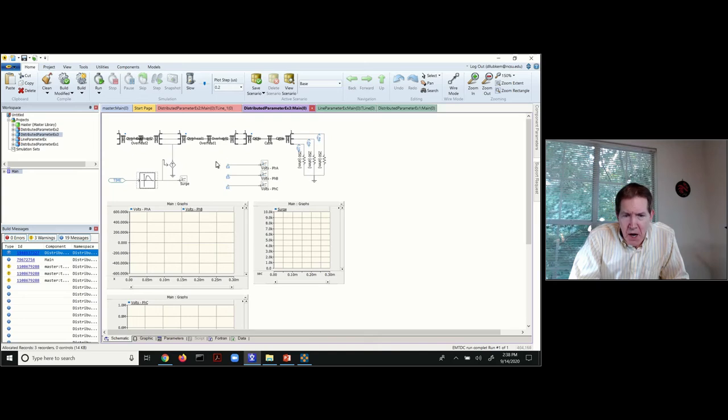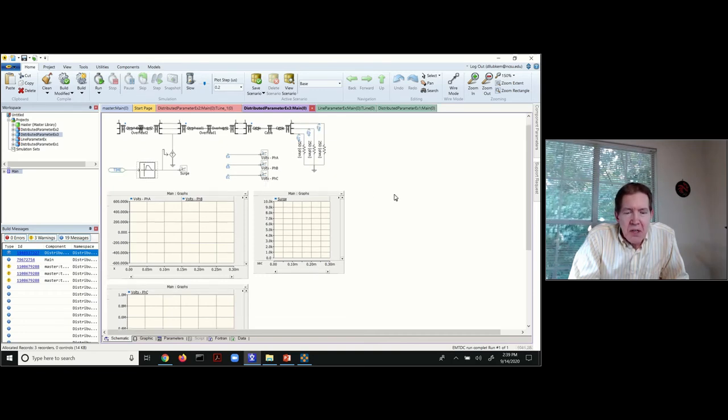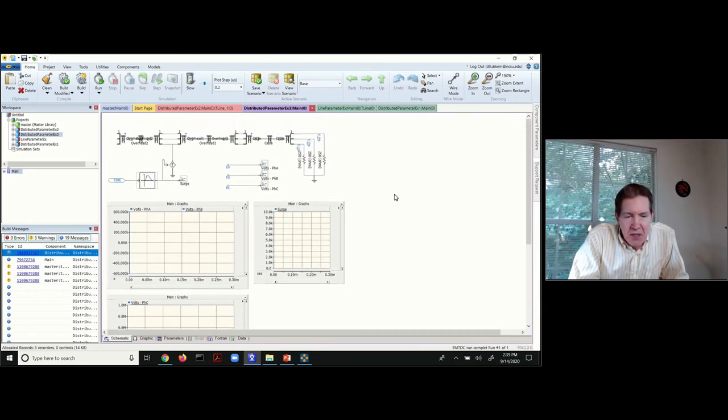And so what I'm doing in this case is I got measurements at various points on the circuit right here, but on the load I'm putting all 3 phases on here so I could see what's going on. And what you would think is going to happen, if this is being injected into phase C, is I should see most of my change in the voltage on phase C, but because of the mutual coupling, I should see something on the adjacent phases as well.